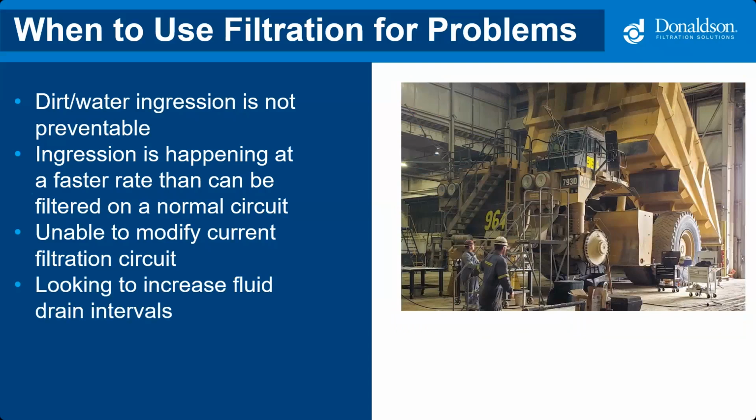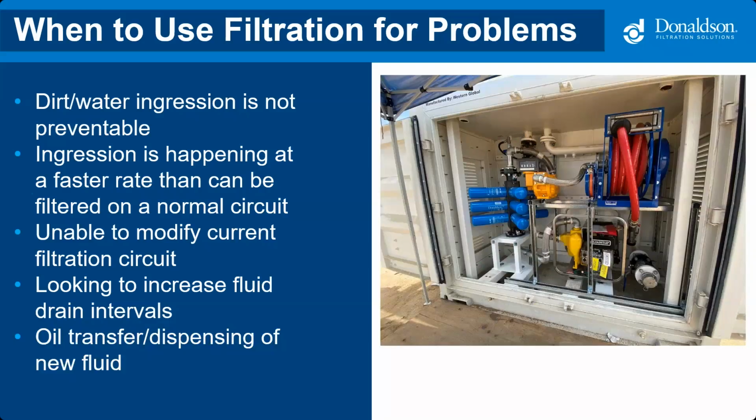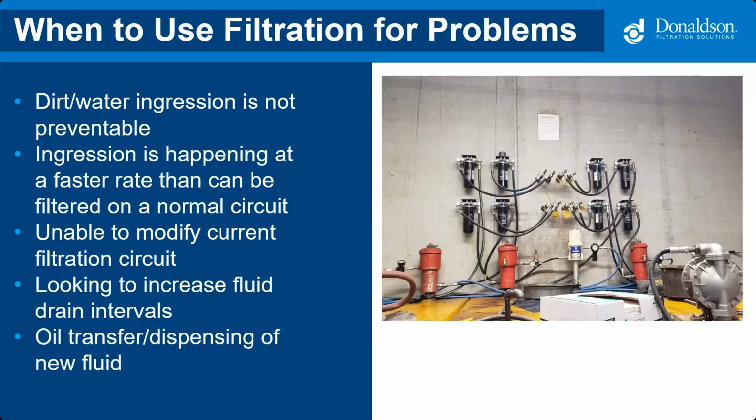Or maybe we're looking to increase drain intervals. A lot of times fluid is replaced because it's become too dirty to be used, but the actual additive packages and the chemical makeup of that hydraulic fluid is still fine. Or even the transferring of new fluids, whether that be fuel or bulk lubricants, making sure that those fluids are cleaned as well, and we can use some of those offline filtration principles to solve that.